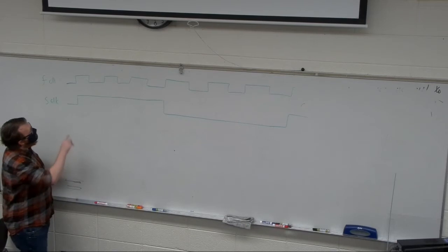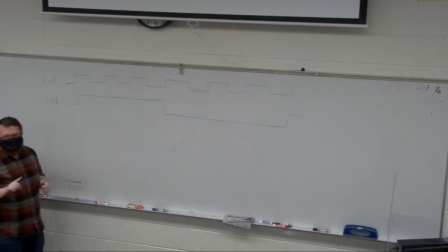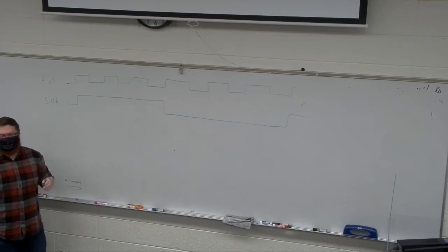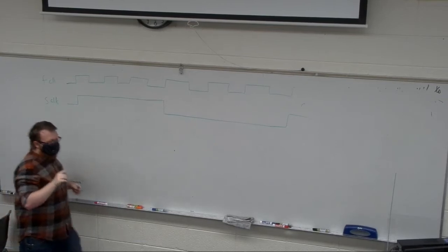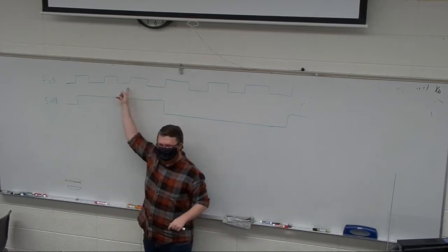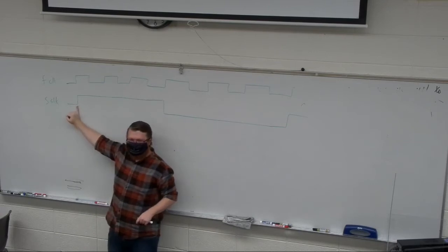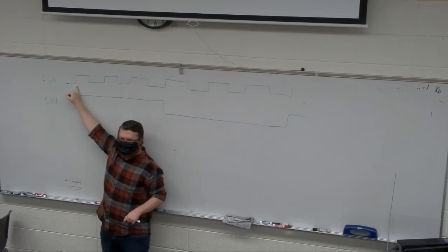What we don't want is a situation where these 2 clocks are trying to sample the data, right? So we're going from the slow to the fast. The issue could be that if I update the data in the slow domain here and try to take it in the fast domain at that same time, we have this metastability issue, right?